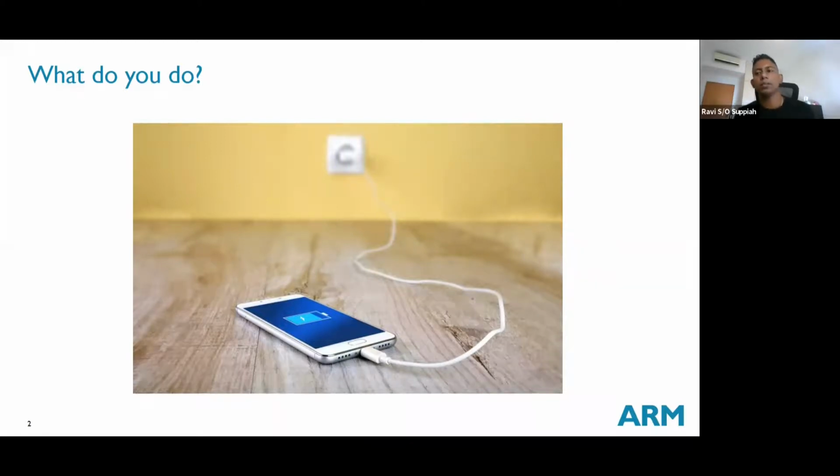Is the PWM signal actually coming out? If the PWM signal is in fact coming out, then you know your code is fine. Correct? Then the next step is, okay, the hardware side. Did my motor driver, did I connect up the circuit correctly? Have I applied the power correctly? Correct? So that is how you must approach and try to troubleshoot when you see issues.